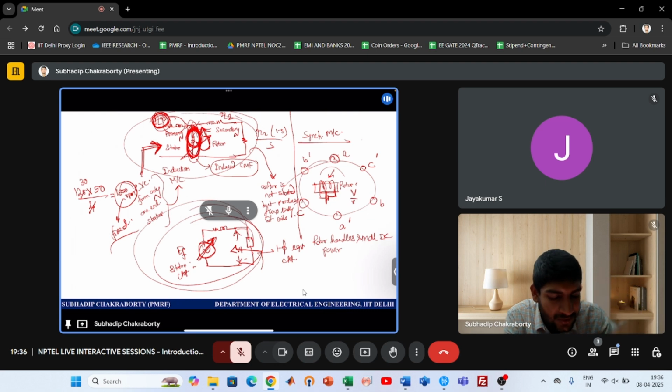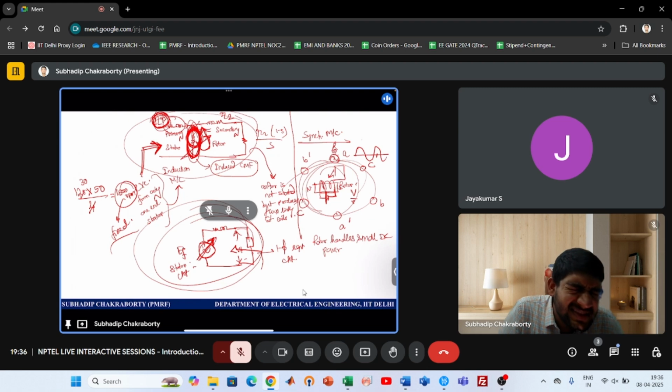If you sit on one coil and this kind of magnet is cutting it while rotating, when the magnet is there, this coil generates maximum EMF. Then it falls, then it rises like this. So it generates AC voltages. So a DC rotor cutting the conductors of the stator also produces completely AC sinusoidal voltages.